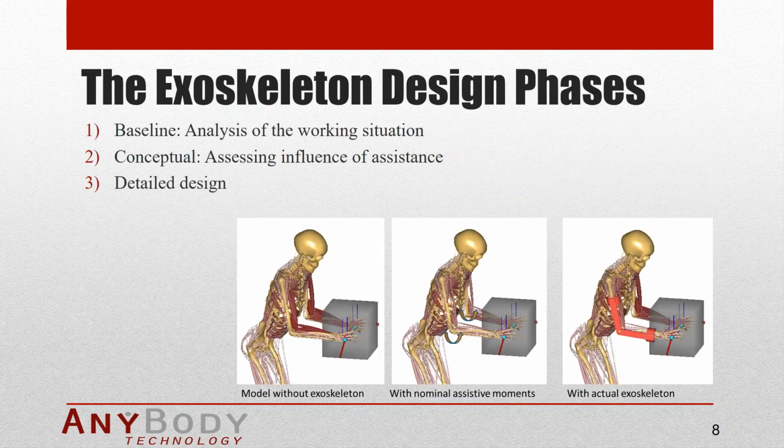So the way I see exoskeleton design phases is just like designing any other product, actually. When you're designing some sort of product, you go through a sequence of processes where you begin with conceptual design. So you're coming up with general ideas for how the product is going to work. And then gradually the designs become more detailed, and you go from the conceptual design to the detailed design phase. It's also like that with exoskeleton design, but there is an additional design phase that I think comes before the actual design of the exoskeleton, and that is what we can call the baseline analysis. That's the biomechanical analysis of the working situation that you want the exoskeleton to be helpful with.